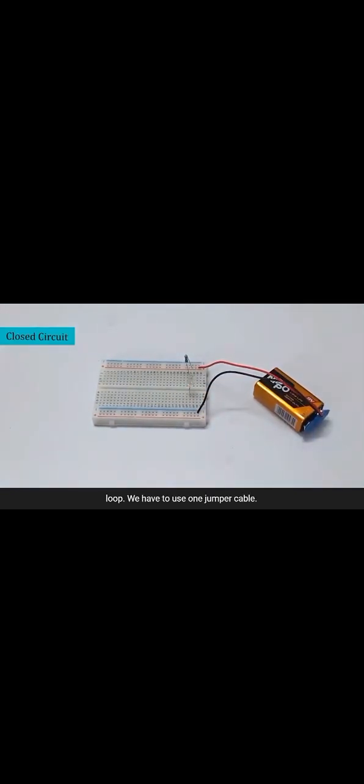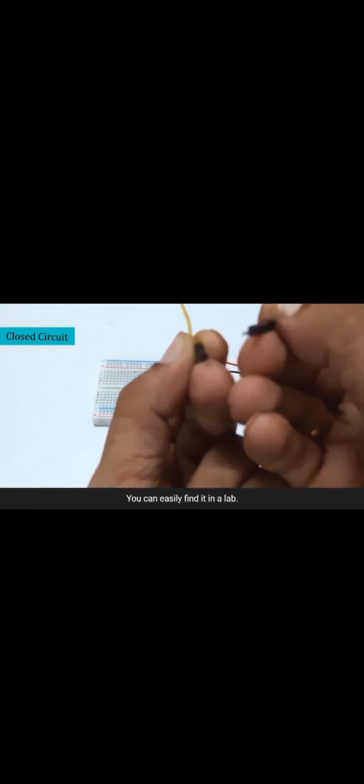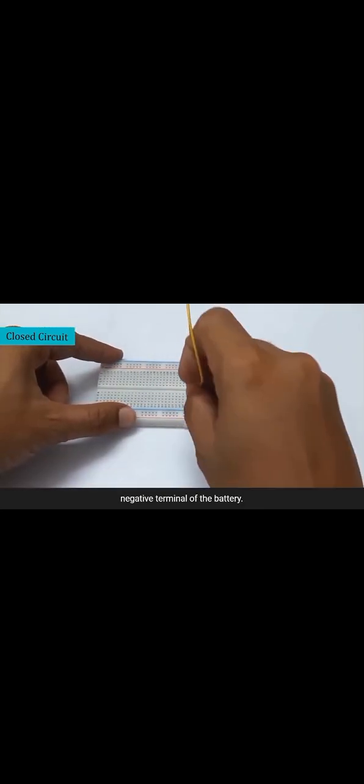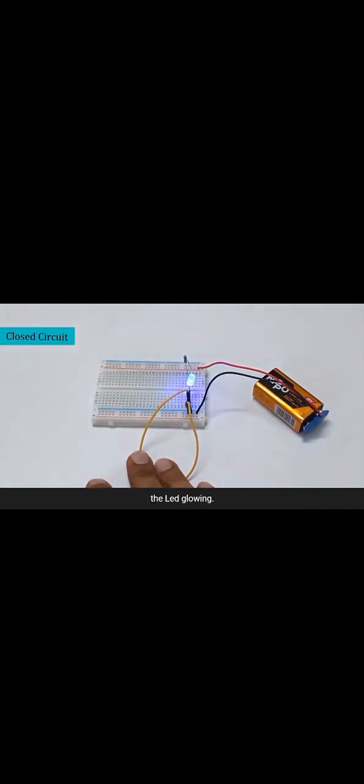To make it a closed loop, we have to use one jumper cable. This is a male to male jumper cable. You can easily find it in your lab. I will jump the cable from the negative terminal of the LED to the negative terminal of the battery to close the circuit. The moment I close the circuit, you'll be able to see the LED glowing. The LED will glow the moment the circuit gets closed. So this is a closed circuit.